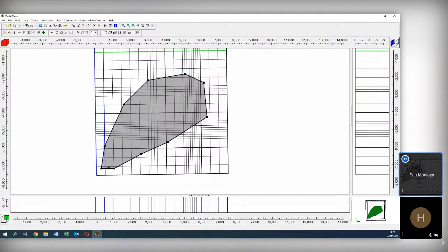Okay, and let's say, like Javier says, to couple with your study area. For example, if you have a preferential flow, say a leak from a tailings dam, and you know the direction of the leak, you will rotate your grid in order to match this direction. Okay, so these are some reasons, and there are many reasons why you rotate.